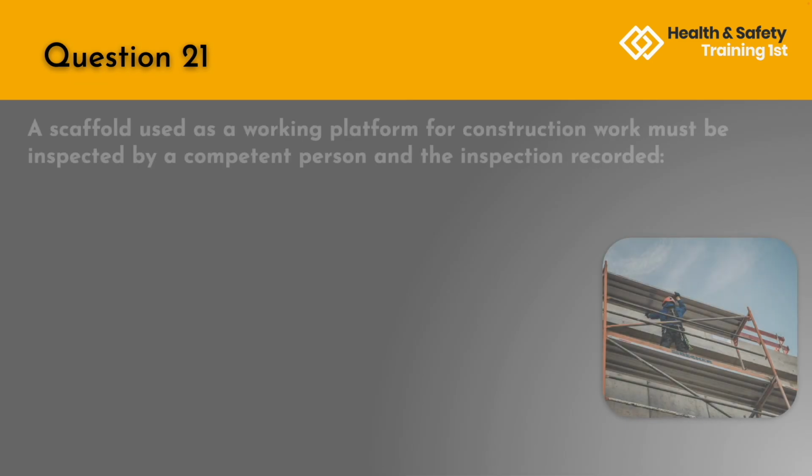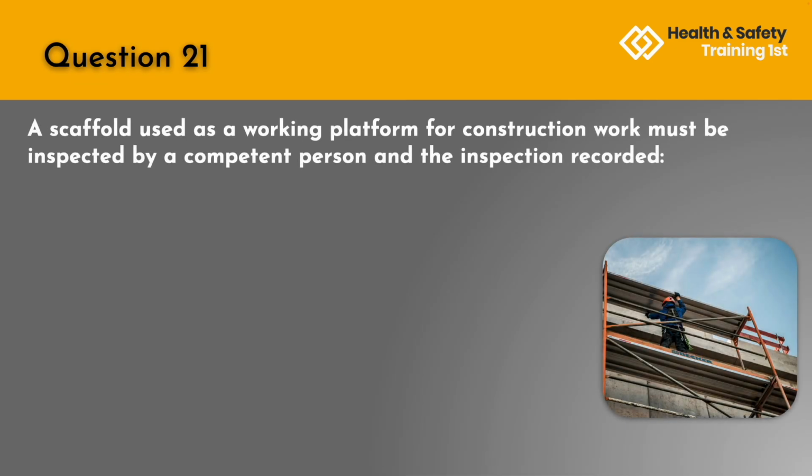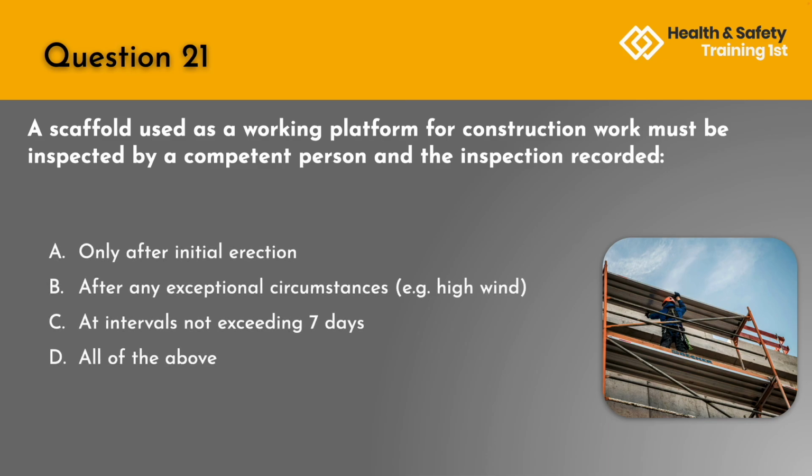Question 21. A scaffold used as a working platform for construction work must be inspected by a competent person and the inspection recorded A. Only after initial erection. B. After any exceptional circumstances. C. At intervals not exceeding 7 days. Or D. All of the above.